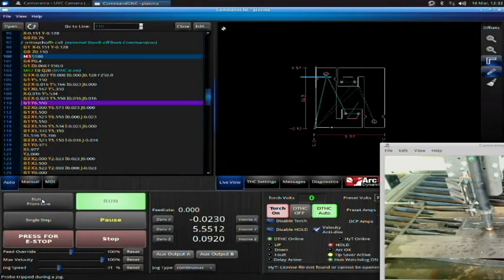So first, I encourage you to practice that last error because that's the most common error you will find. So an error on a pierce. Okay. Step one, hit the stop button. Figure out why your plasma cut. Go up to the previous M3 or M5. Click on that line and then go run from line. Okay.